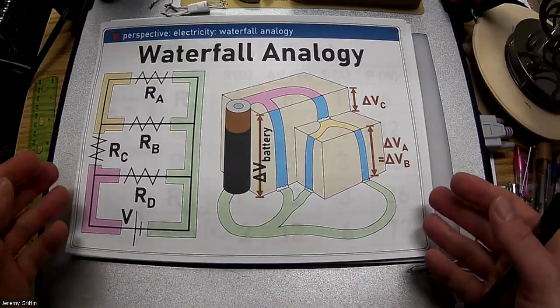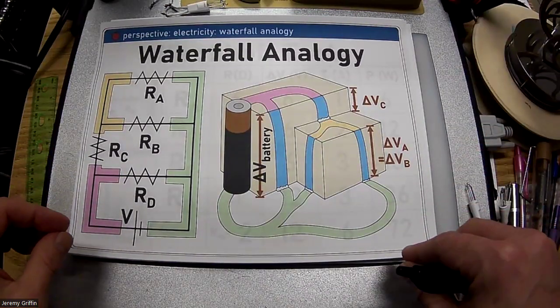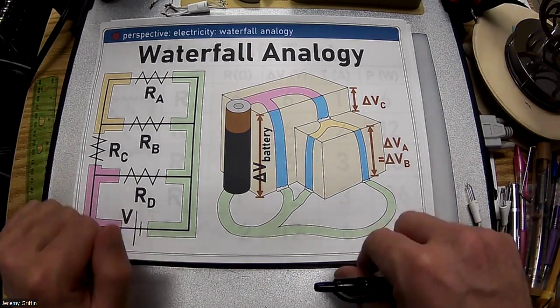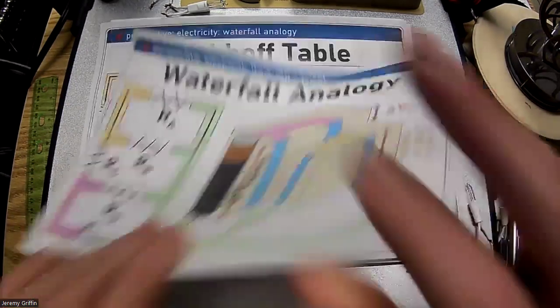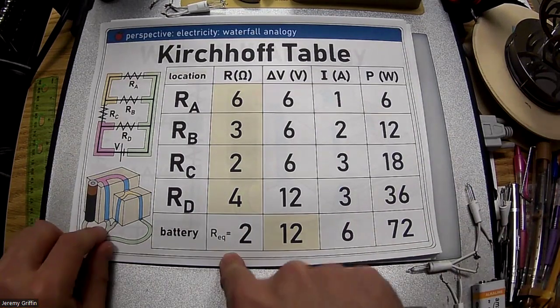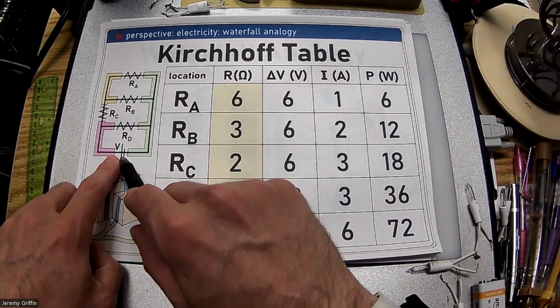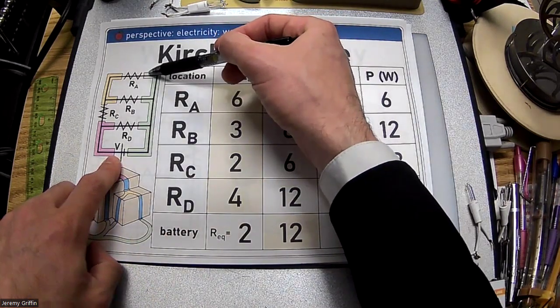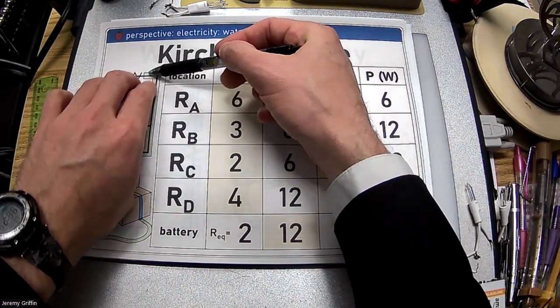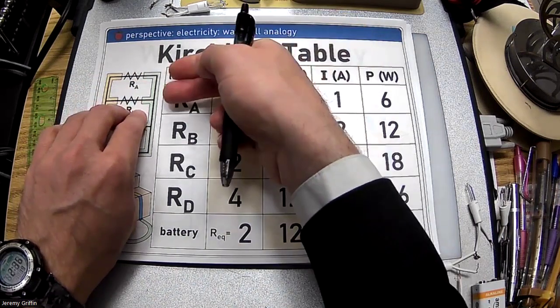And the last few things here today: what if you have some hybrid system, something that's not exactly series and not exactly parallel? There's a process for figuring this out. If you want to figure out the total equivalent resistance, you start at the point of the battery, you fly over to the opposite side of the circuit, and you work your way back and find equivalent circuits.